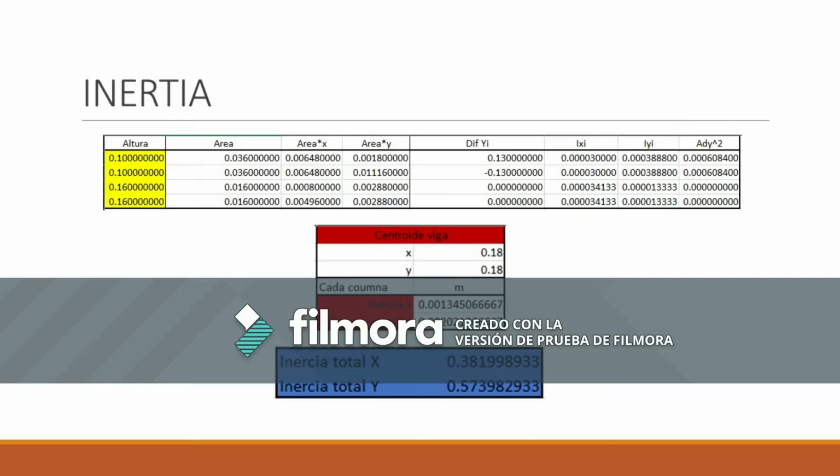As we can see in the blueprints, the distribution of the columns at the 80th floor, the next step was to multiply the inertia of the column calculated by the total amount of the columns of that floor. And we can say that we calculated the total moment of inertia about the x-axis of the floor. Moreover, we calculate the inertia about the y-axis. Since the columns have the shape of a square at the base, the moment of inertia is the same for both axes.